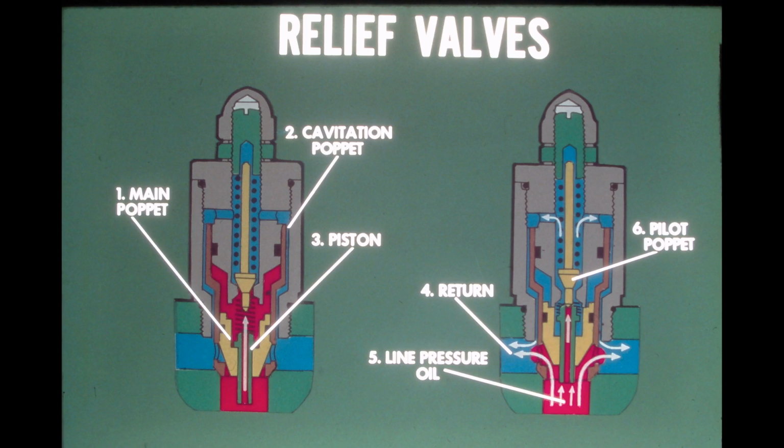With the piston backed up to the pilot poppet, the effective working area of the poppet is increased, since, in this position, it includes the lower face of the piston as well. This added working area will cause the pilot poppet to hold open until the pressure drops about 100 psi lower than the cracking pressure. This open to close pressure range prevents chattering and reduces the workload on the poppet and other valve components.